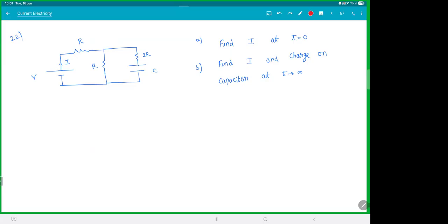T0 done? Be careful, at T0 the capacitor becomes a wire. Draw the circuit. Always draw the circuit. T0, T infinity, draw the small circuit, you'll understand. Try. Whatever you think, do it. It's okay to get a wrong answer. Param, get me the charge also. 3V by 4R, 4 won't come. You goofed up, I guess. Check there. Samyak, that is right.